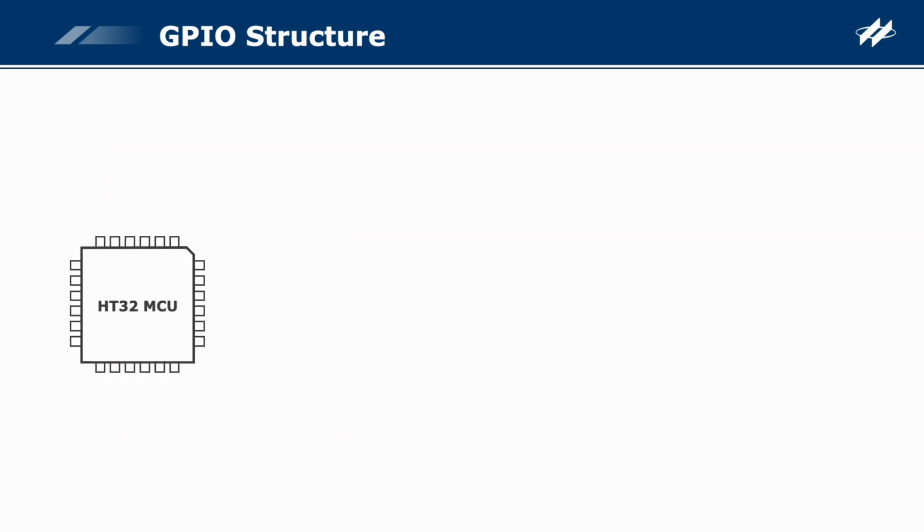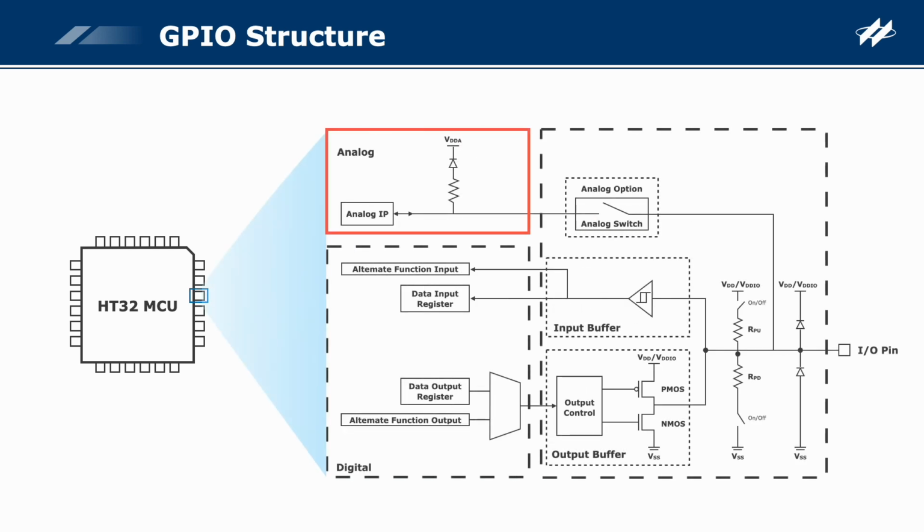After a basic understanding of the MCU GPIO terminology, let's go on to learn about the internal structure of the MCU GPIO ports. This is a simple GPIO internal structure diagram, including pull-up, pull-down resistors, analog area and digital area, etc. The GPIO pins are used to support the MCU peripheral communication. For basic applications, they can be divided into analog area and digital area. This topic is GPIO, which is mainly used for digital input-output, so we will focus on the GPIO digital function.